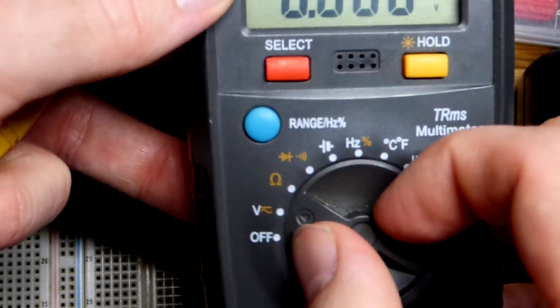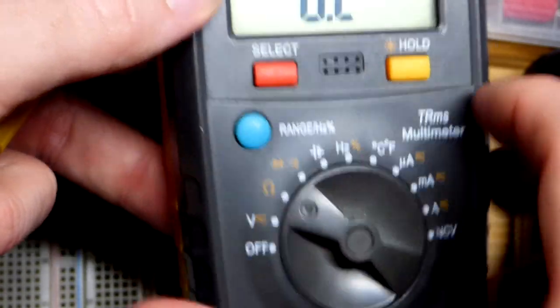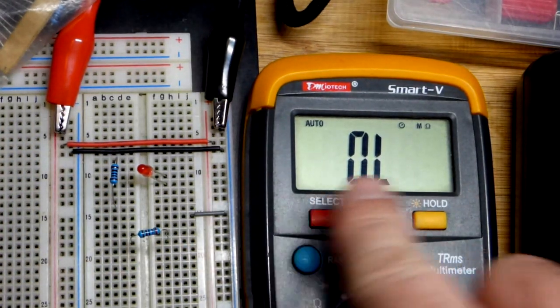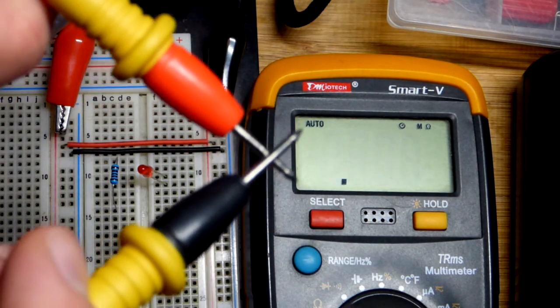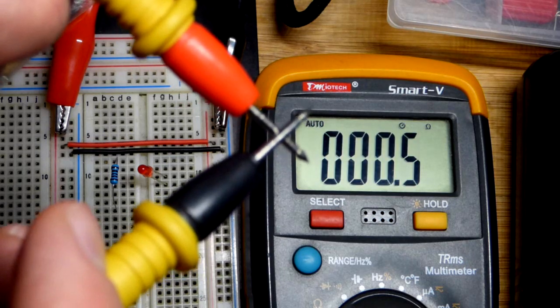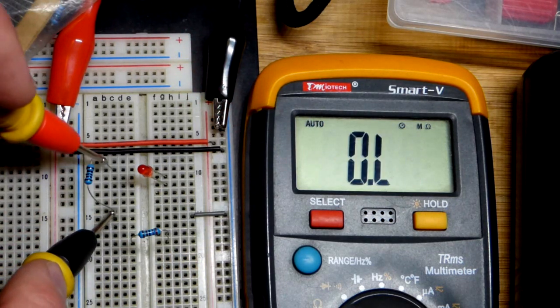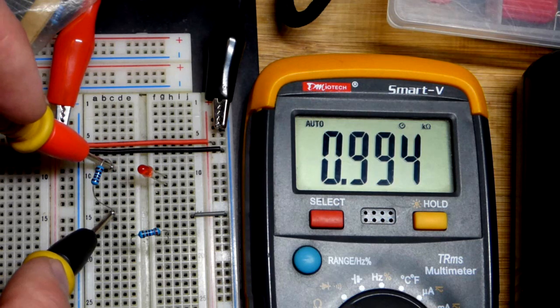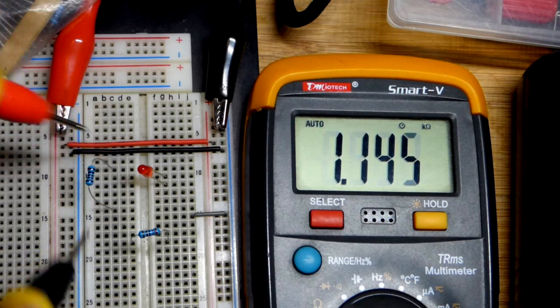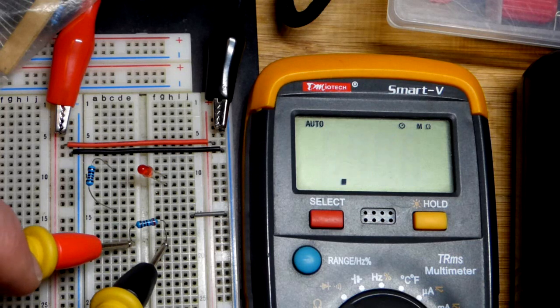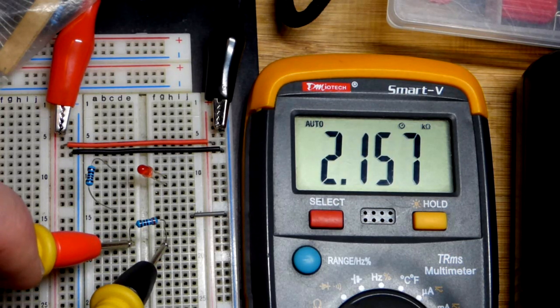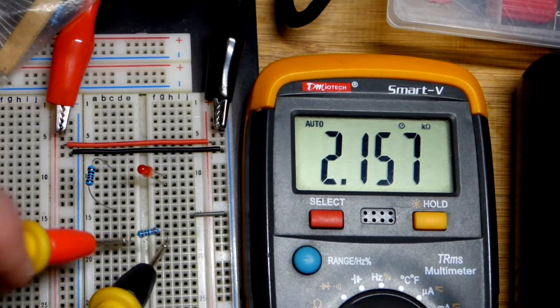So our next measurement is going to be resistance. Again, auto-ranging meter, all I have to do is set it to the omega symbol. It shows overload. That means there's a lot more resistance between these two probes right now due to the air than what it can measure. You can see we got pretty much 0 when we connect them together. So this is our 1,000 ohm resistor, and it looks like it's a little bit shy, unless the meter is a little off. I don't have 2,000 ohm resistors, at least not in the main kit I use. I have 2,200 ohm resistors, and this one looks like it's a lot more shy than maybe it should be. But in any case, it's about 2,200.